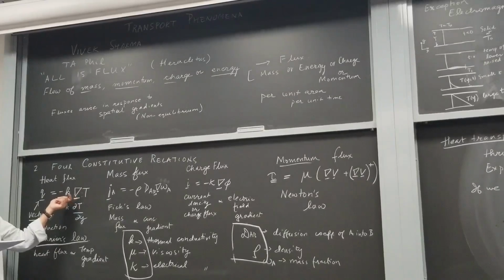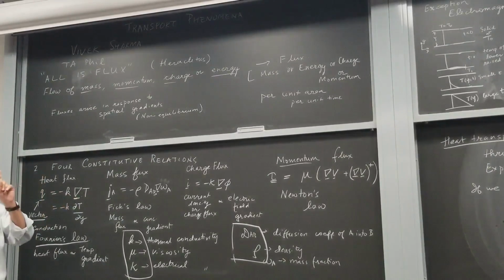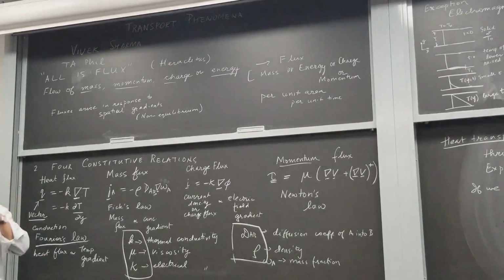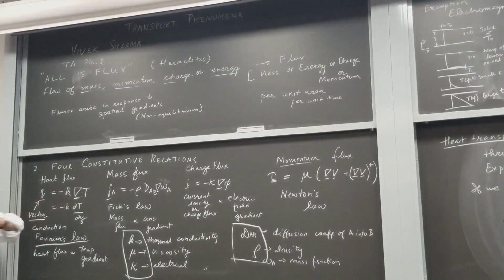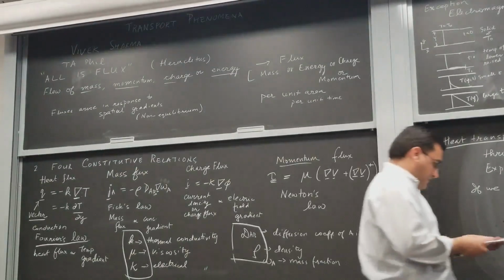We later will discuss how this constitutive model assumes isotropic, which means there's going to be the same conduction properties in all directions. That's true for a material that has the same properties in all directions. Now if I take a composite, which I can make by taking metal wires, and metal has higher thermal conductivity as well as electrical conductivity, and then embed them in a plastic, in the direction of the wires there's probably going to be higher conduction. In any other direction, it's going to be lower conduction. In fact, the specific direction you're looking at becomes so important that we'll need to replace this with a tensor. Thankfully, we're not going to do any of that in this class. It's just for completeness, we'll mention that in some detail later.